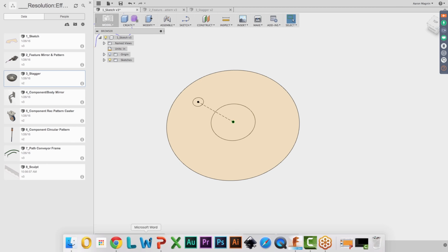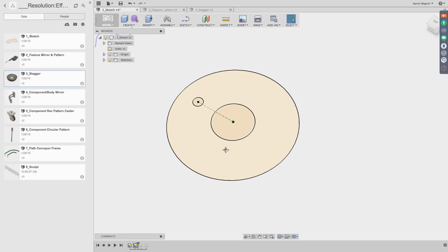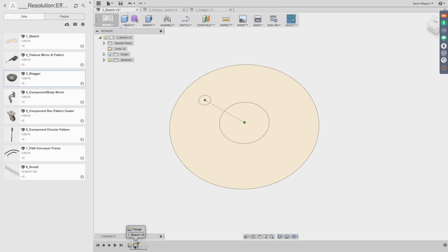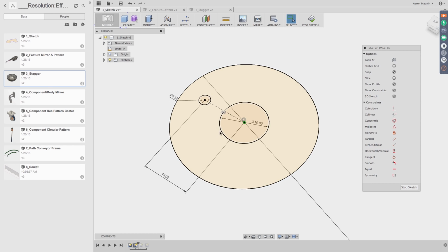I'm involved in a project where we're doing just that. So hopefully we see some of the benefits of that shortly. But to go back to editing that sketch to do what I originally intended to do, I'm just going to double click on the sketch once again to get into editing it, and using the drop down I can now select that circular pattern.